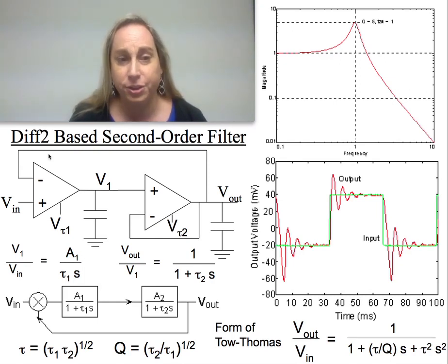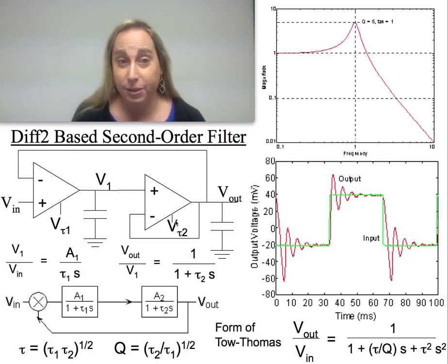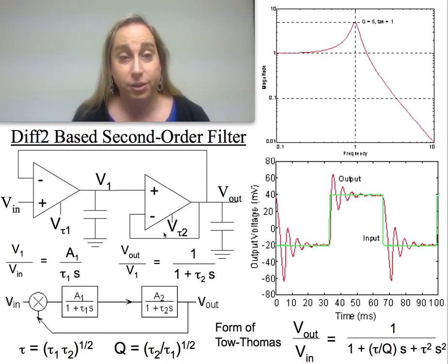The core of the structure is basically two OTAs. Again, I may have a voltage bias that I can control, which then sets whatever its transconductance is. These might be physical biases, or things that may be loading cases that you're setting. A number of things are possible. If you look at the structure, the first element looks like an integrator, a high gain structure, and the second looks like a low-pass filter, a unity gain topology. And then I build the feedback all the way around it.